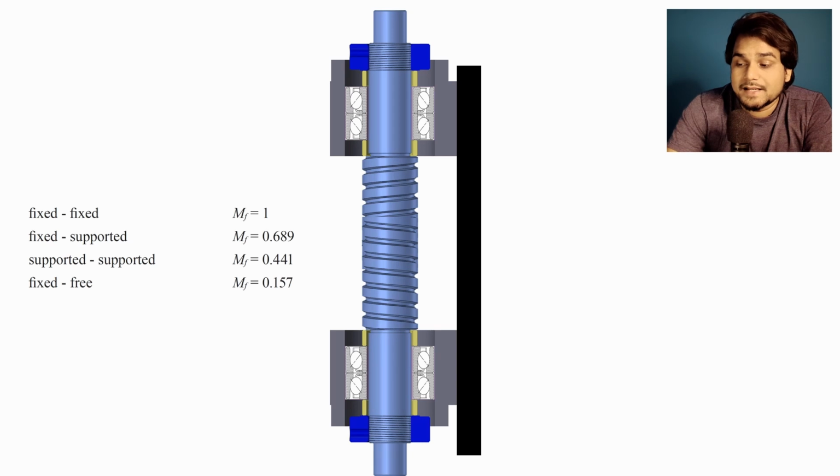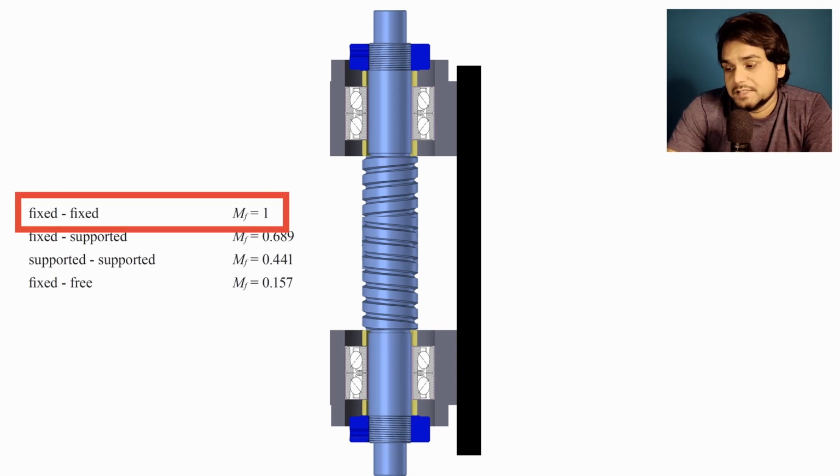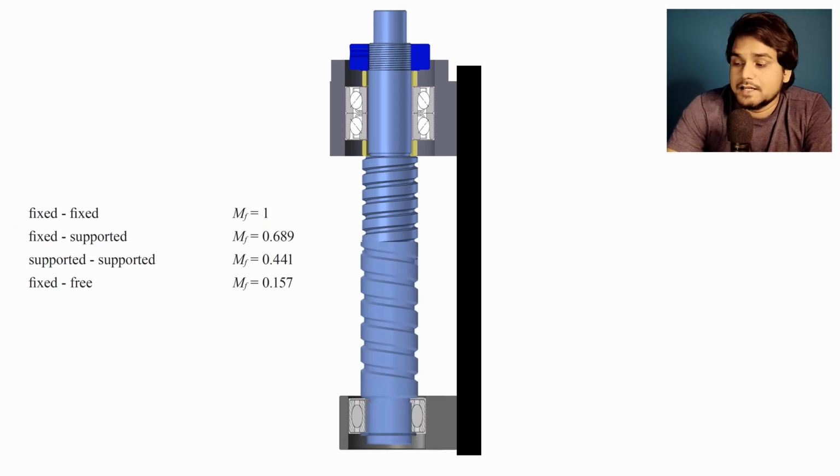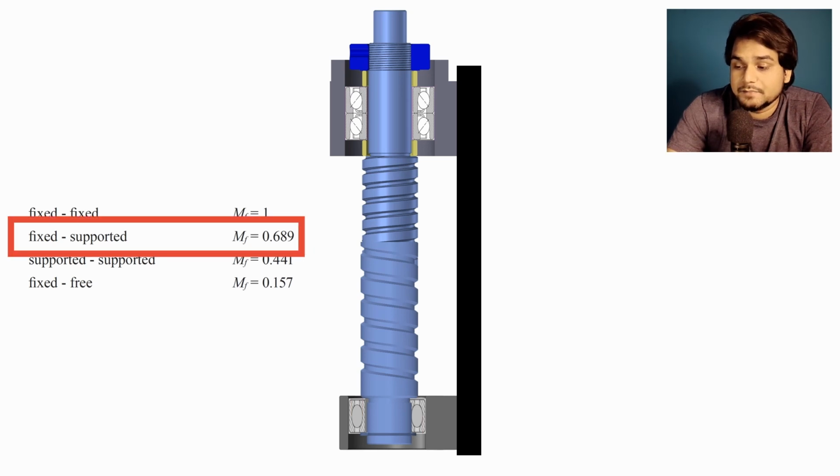If the thrust load is high and you are designing for a vibration condition, then you can use fixed bearing blocks at both sides. And their bearing support factor will be maximum, which is 1. And for the fixed float bearing arrangement, the bearing support factor will be 0.6.